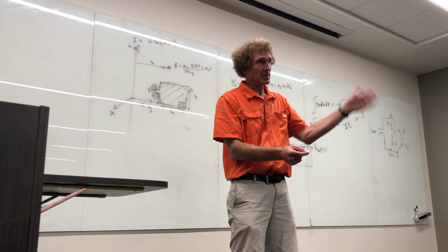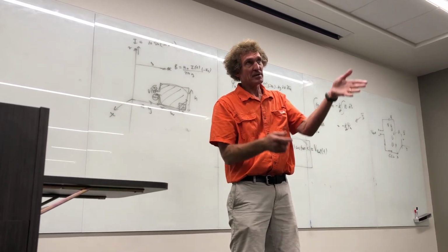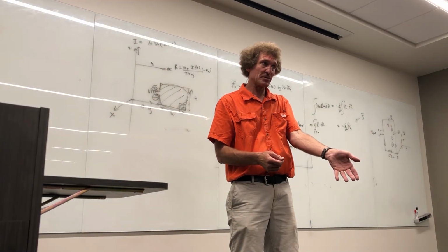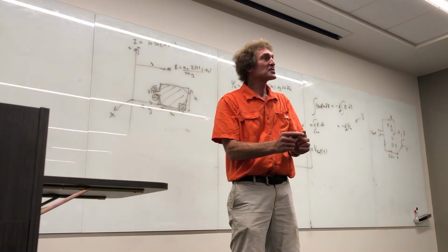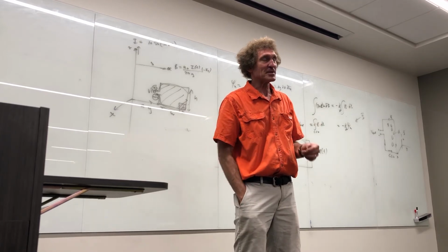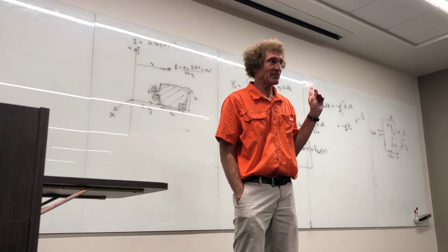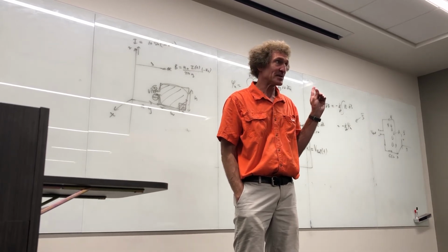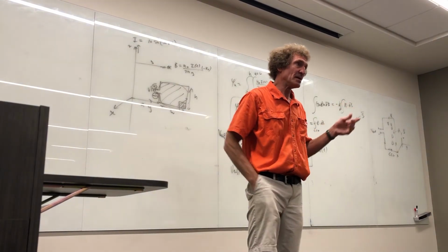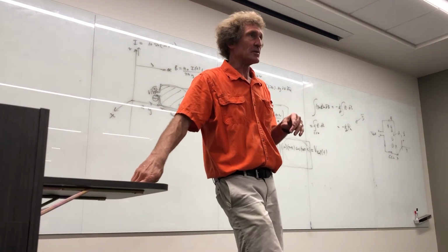And lightning creates a big B field, and it theoretically would induce a large flux change through those wires, and there's N turns there, right? And you just might see a spark. Every time there's lightning, you would see a spark. Now what's interesting, that's one way of detecting lightning. If you had this inside a building, you could do this, and you would know there'd be lightning outside, assuming it's not solid metal, because that would shield it. But if it had porous concrete or something.